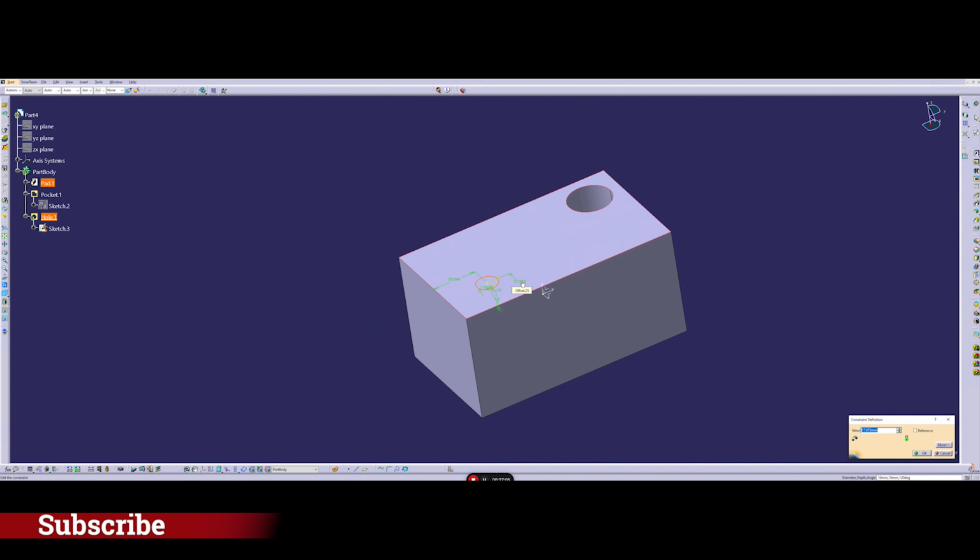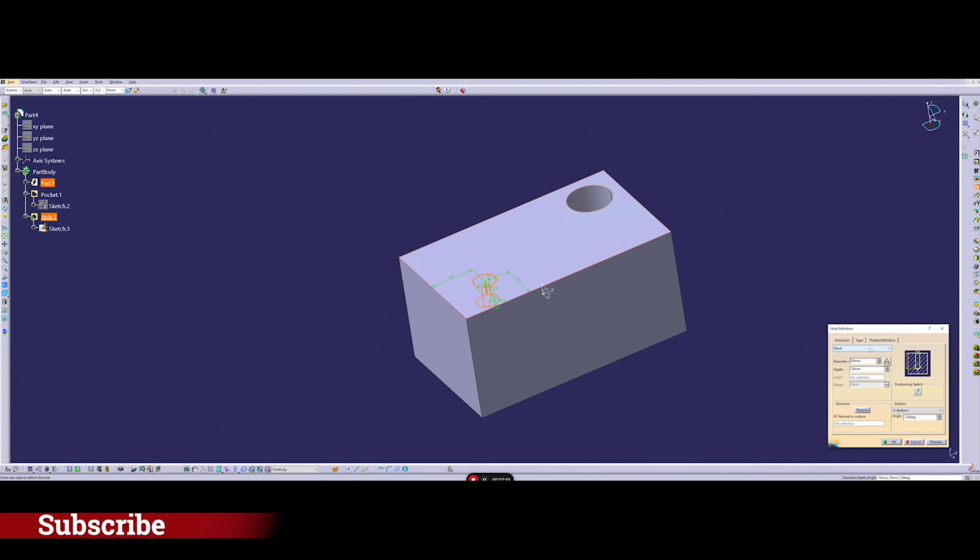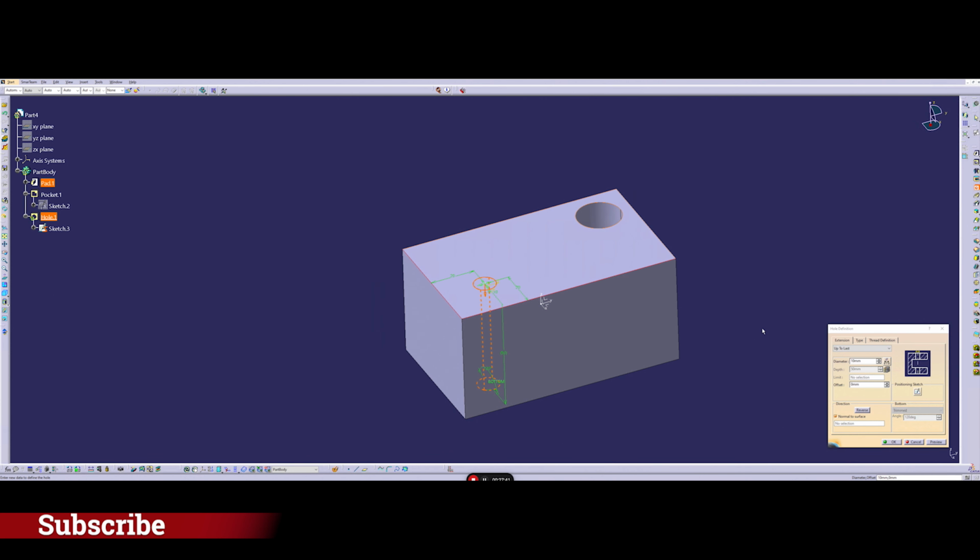And here what you can do, you can change by double clicking the dimension. So here let's go to 20. Here I want also to go to 20. And now you see that I'm 20 millimeters from this edge, 20 millimeters from the other edge. So down here, first of all, you have to choose about your hole. Your hole can be blind, or can go through the whole part, which is up to last, so we'll go up to the end of your part, which is what we want to do now. And of course you can choose the diameter. Okay, the diameter here will be 20 millimeters.